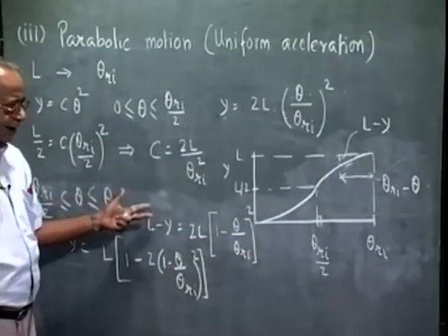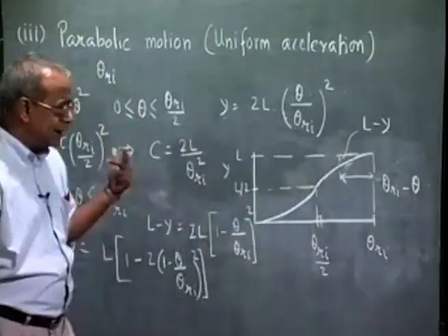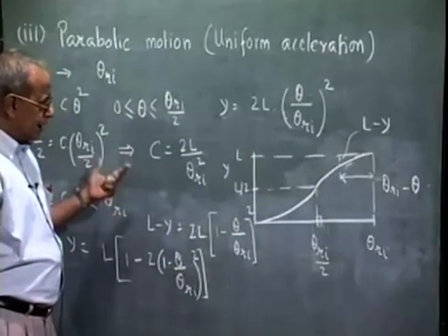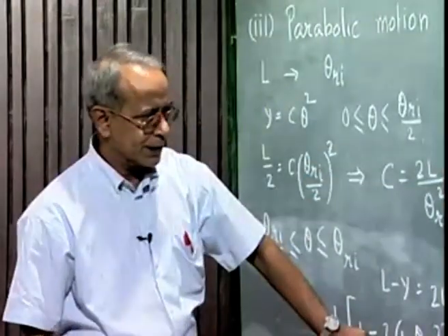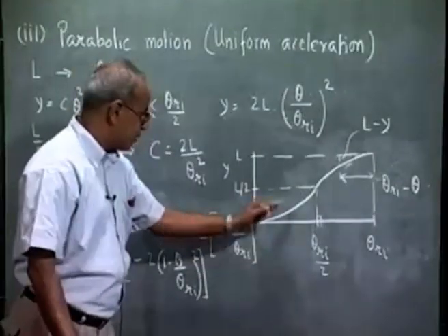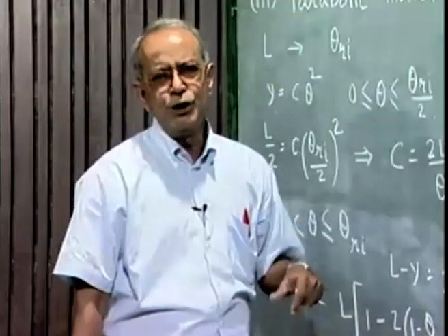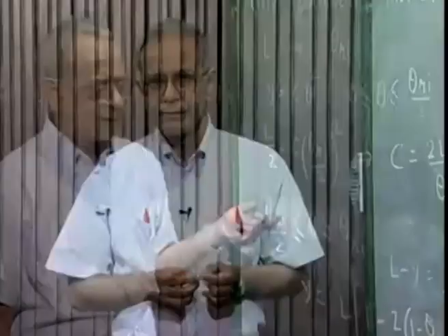Next we shall discuss how do I draw this parabola graphically, because we may need to draw the displacement diagram graphically in case of graphical synthesis of the cam profile. These are the analytical expressions. Of course, we can take the values of theta and y and plot this graph, but there is a simple way of drawing a parabola which you must have learnt in your drawing course, but let me just recapitulate it.